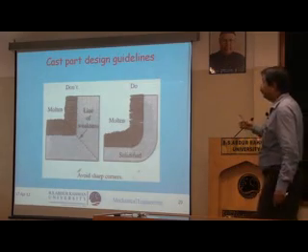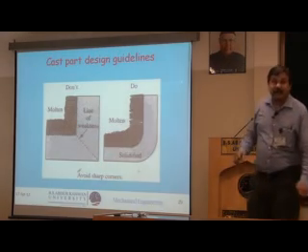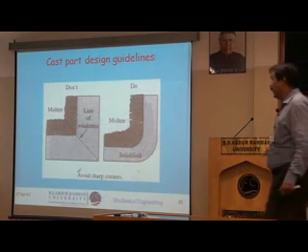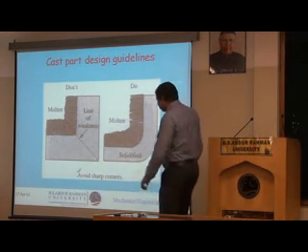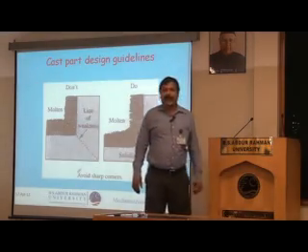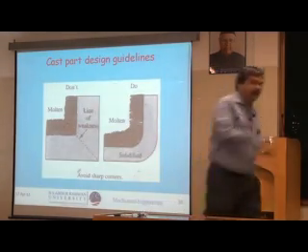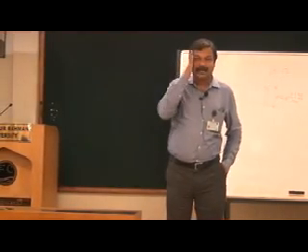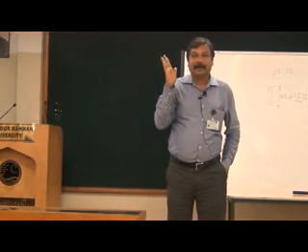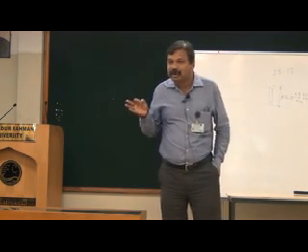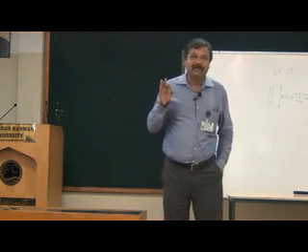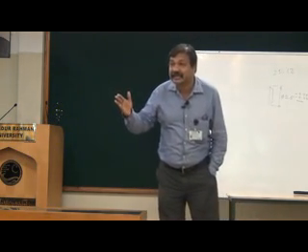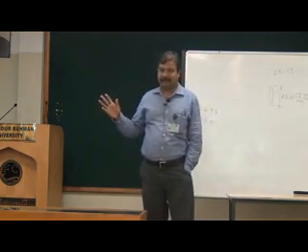Now, this is for when you are designing parts for casting. In casting, as I told you, we melt the metal and pour it into a cavity, and in casting you should never forget this. The least melting point constituent is going to be the one which solidifies last, and that is going to be the weakest part of any casting.